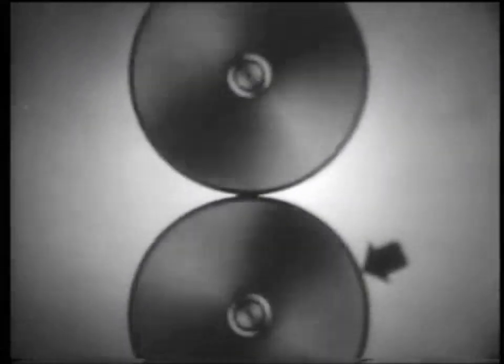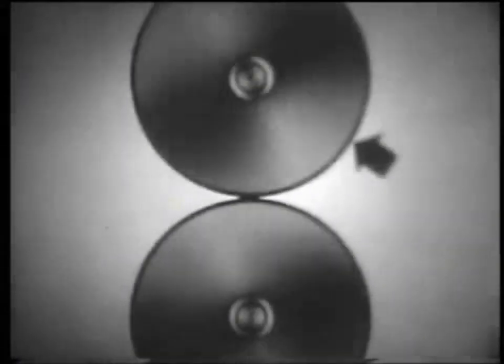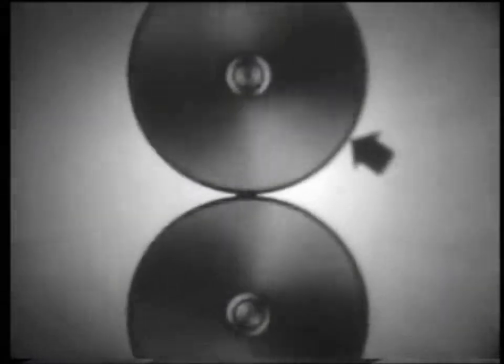Let's get acquainted with possible damage to the working surface of the gears. If the contact stress exceeds the permissible one, fatigue pitting occurs. Using the example of two rollers, one of which rotates slower and the second faster, you can show the mechanism of fatigue pitting. On the leading surface, the friction forces are directed against the movement, and cracks are directed against the movement. The other surface is lagging behind in movement.